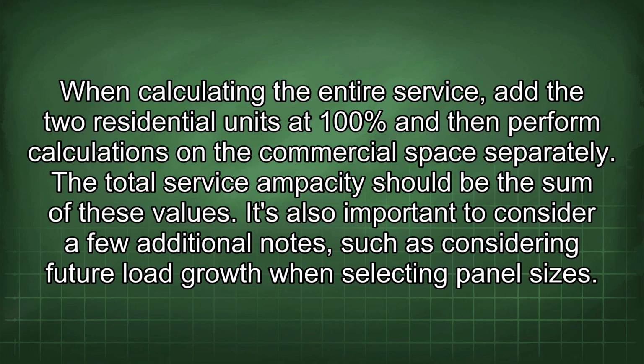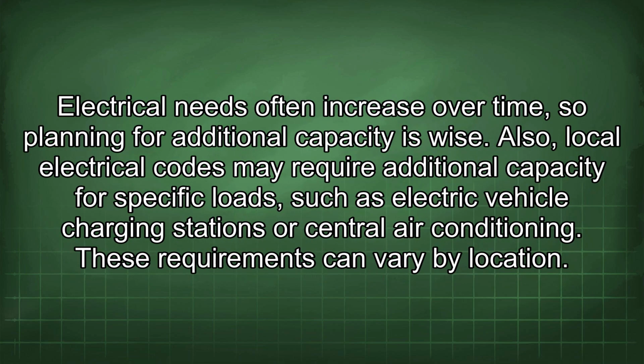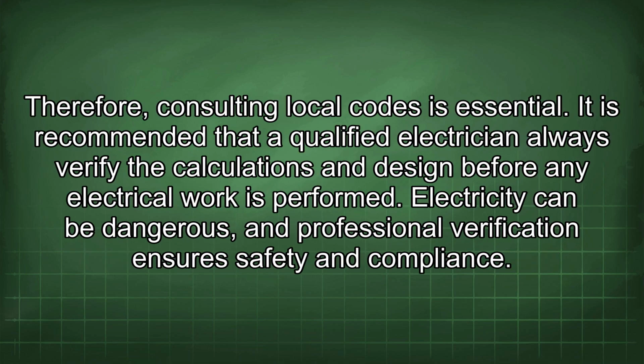It's also important to consider a few additional notes, such as considering future load growth when selecting panel sizes. Electrical needs often increase over time, so planning for additional capacity is wise. Also, local electrical codes may require additional capacity for specific loads, such as electric vehicle charging stations or central air conditioning. These requirements can vary by location. Therefore, consulting local codes is essential.